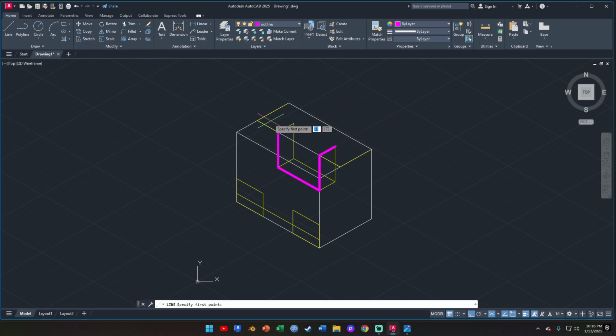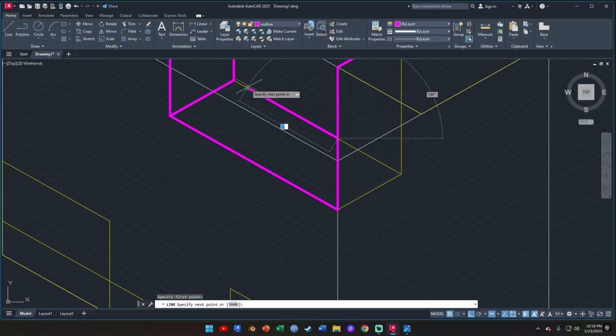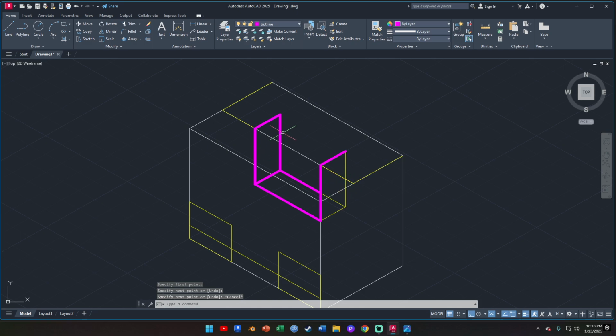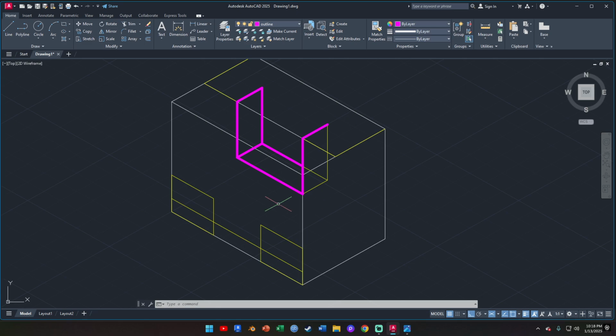this here, and these lines, right? So you're using the outline layer to basically show what would be shown and what would not be hidden, because one thing that we do in isometric projection, we do not show hidden details, right?